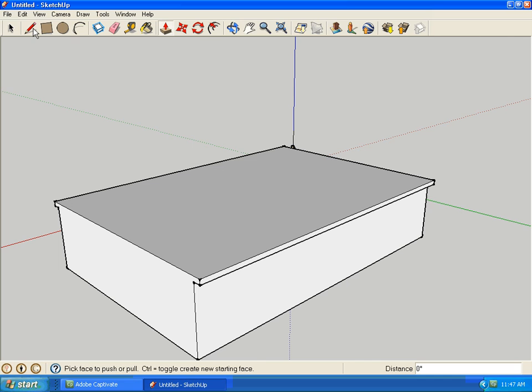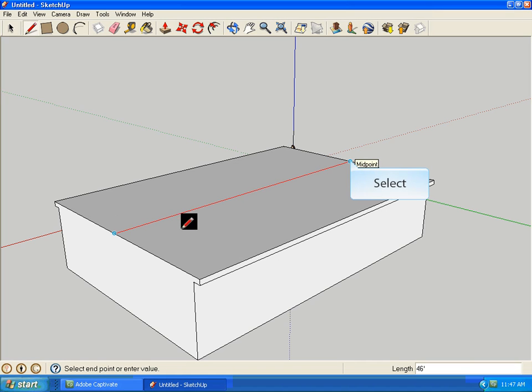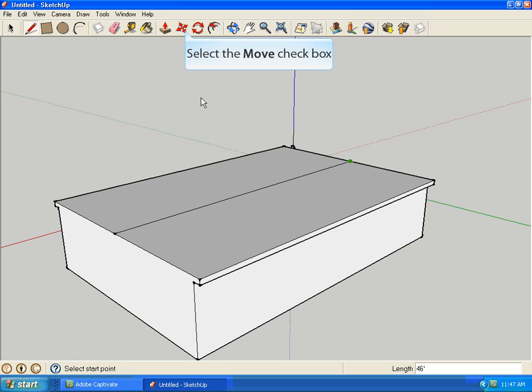Now for the ridge. Click on the line icon in the toolbox and bring the pencil icon down to the midpoint of the left edge of the top side of the prism. A blue dot appears with a flyout saying Midpoint. Click on that blue dot and draw a red line from that point to a point along the x-axis to the opposite edge of the roof. When you connect to the opposite side, you will once again see a blue dot with its flyout. Click on that point.